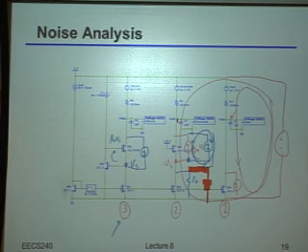But now let me really push on it. Let's say that my 1 over gm of that device is small compared to all of the impedance in the rest of the circuit. Does it matter that that noise current increased, or is it just going to recirculate through the same loop it was circulating through before? What do you guys think? This is one of those times where my tone should make the answer obvious. It's just going to recirculate, right? Because like we said before, putting that amplifier in just increased the effective gm of the device. So yeah, sure, the noise current went up, but so did the gm, right? So just like before, it's going to circulate completely within that transistor itself, okay?